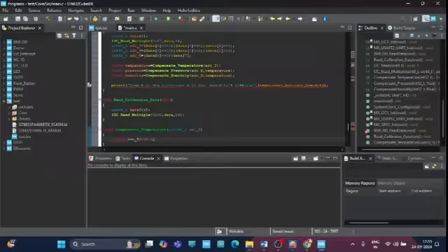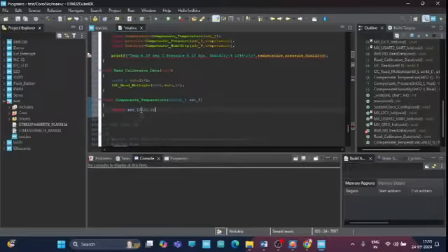That's it. So in this simplified calculation, the raw ADC value is divided by 100 to get the temperature. In a complete implementation, this would use calibration data for more accuracy. Okay, so the same thing will go for pressure.